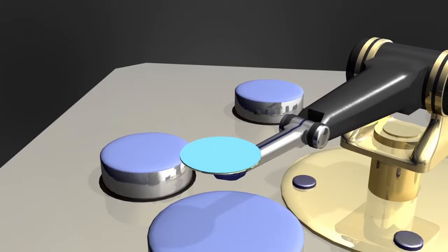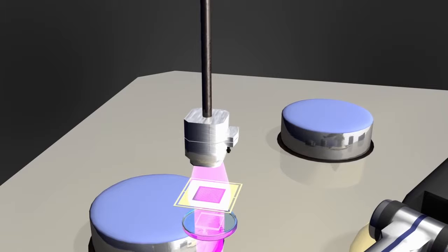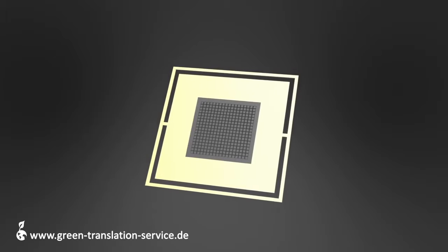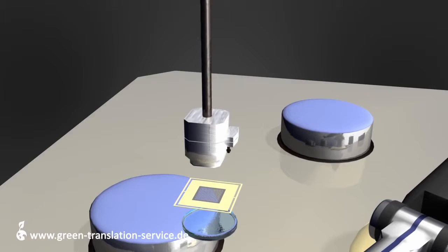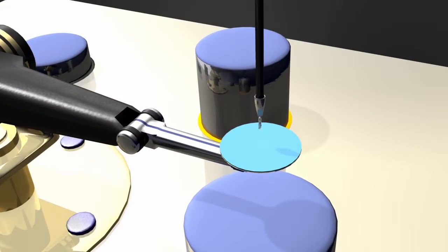In the next step, a prefabricated stencil composed of transparent glass and opaque chrome is projected onto a lens. The lens reduces the size of the stencil pattern. The photoresist becomes soluble wherever it is exposed to UV light. The dark areas here indicate the regions that are to be removed. These can be removed through the application of an appropriate solvent.